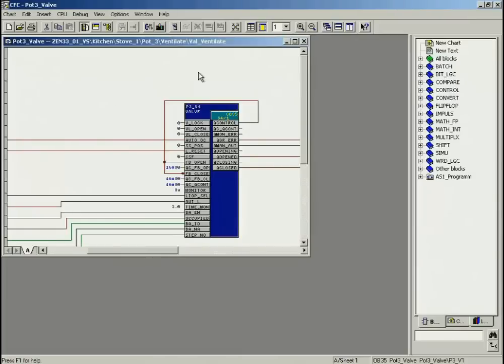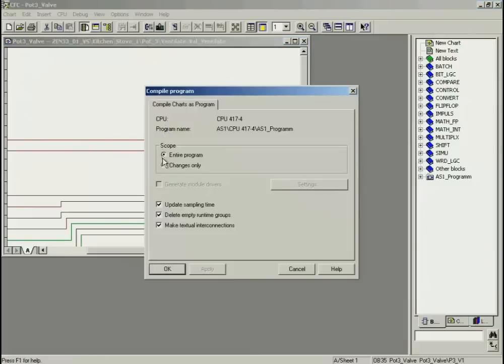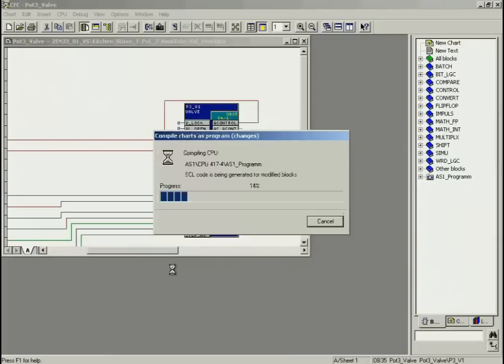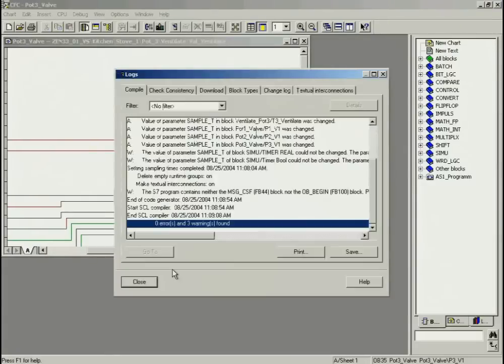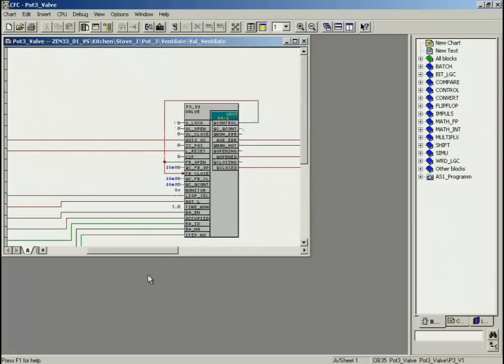All names of the folders, charts, and function blocks need to be adjusted. The charts are compiled, and the data is then downloaded to the automation system. Prior to compilation, a further instance of the phase should be created, or this should at least be pointed out, so that the type instance concept is clearly highlighted. The program is downloaded in the controller.